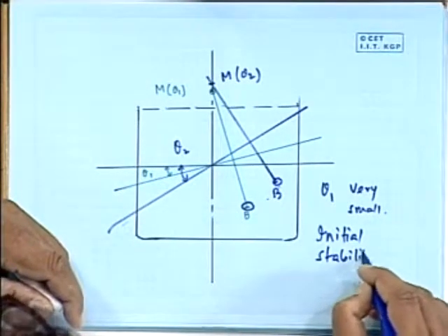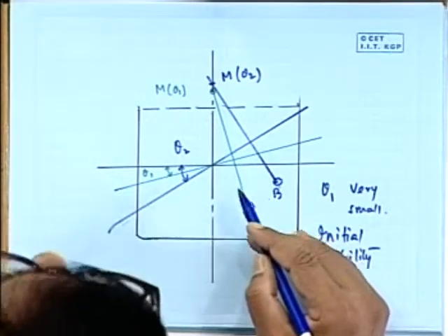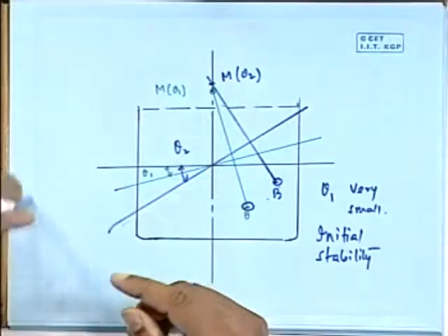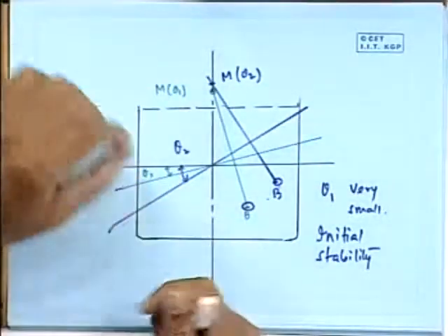is to investigate not whether the vessel is stable when I incline it to 30°, but whether it is stable at all in the 0°. That means, will it stay at 0°? What does it mean? Suppose as the wind blows and it has become 0.01°, slightly shifted, just like I said, if you want to keep that slightly shifted, it will fall. Similarly, supposing the ship is shifted by an angle 0.01° or 0.1° or 1° or 2°, a very small amount, we don't know how much. Should it actually become unstable or not?